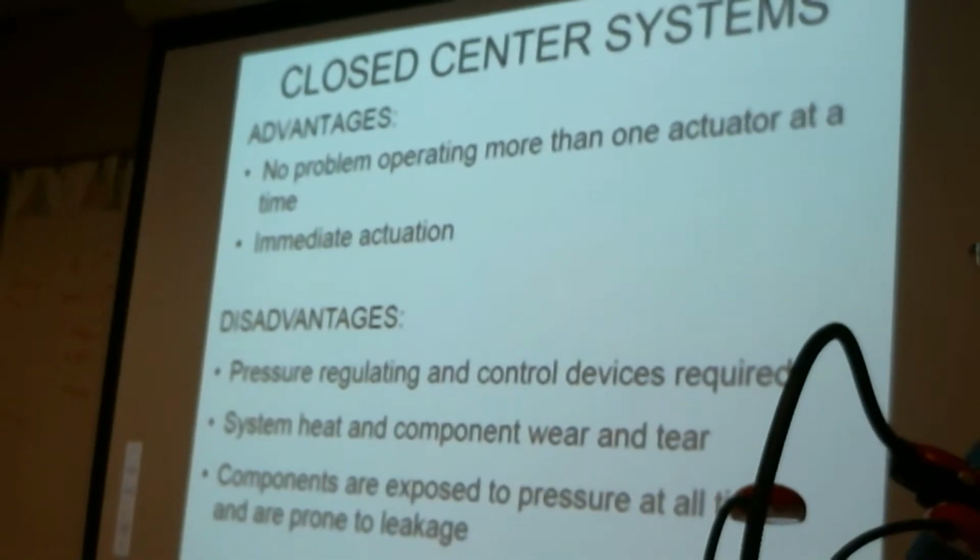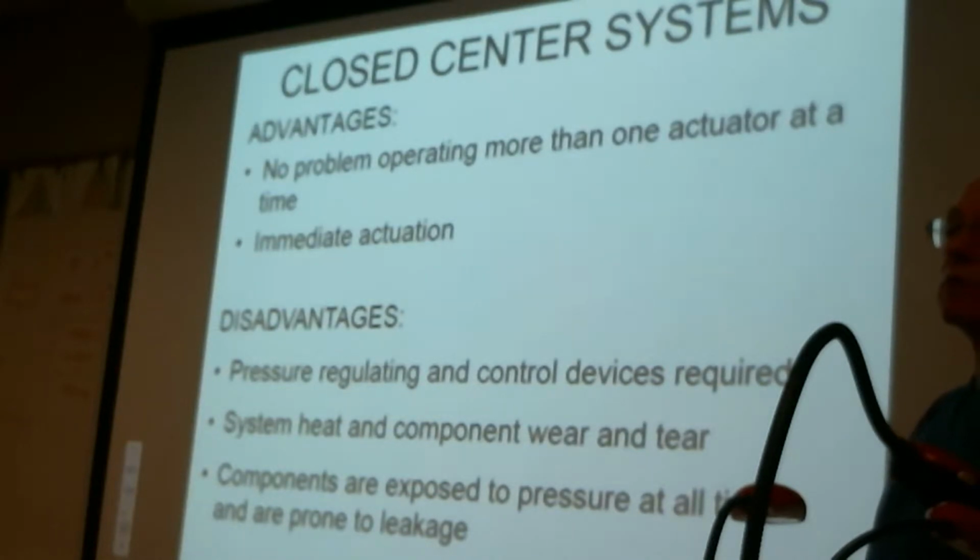Also, because you are holding pressure available all the time, the instant that you open a selector valve, the actuator will start to move. It's not like an open center system where pressure has to build to a point and then the actuator moves. This is immediate. As soon as you expose the actuator to system pressure, it's moving.